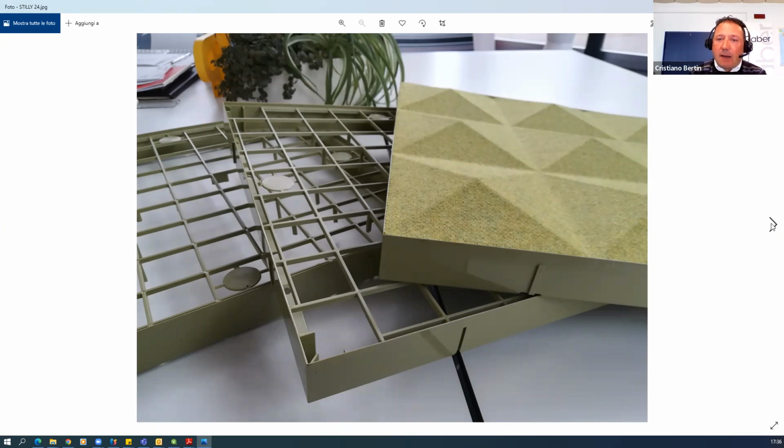Of course, it should not be something that increases the weight of the panels. I'm speaking about Armstrong Ceiling. So this system specifically is just self-supported. There is not a frame on our collection made for the Armstrong ceilings. It's just felt plus fabric. So in this case, it's possible to make holes for sprinklers or whatever, but it's not possible to suspend something with a weight over the panels.